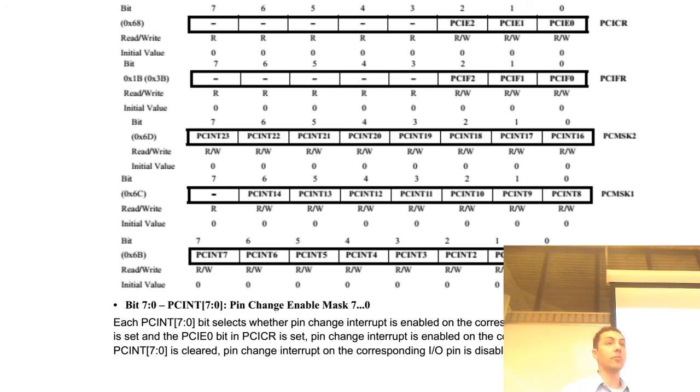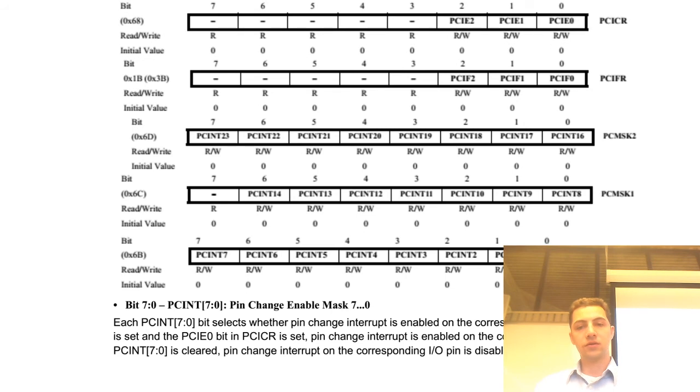Pin change, there's a bit more going on here. There's a control register and a flag register. Same setup. Control register enables. Flag register says, hello, something's happened.